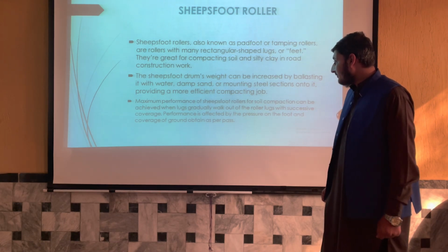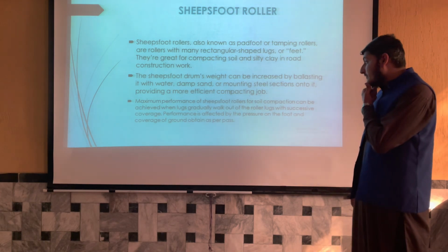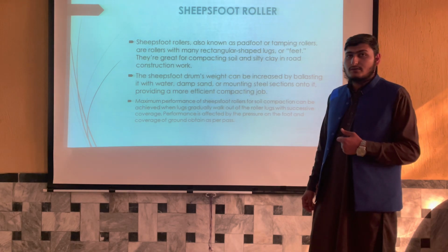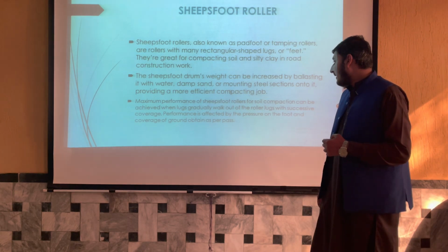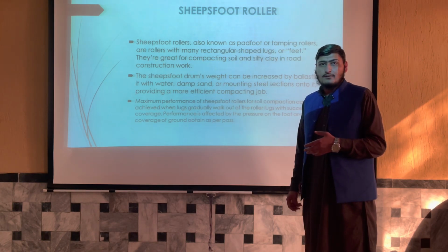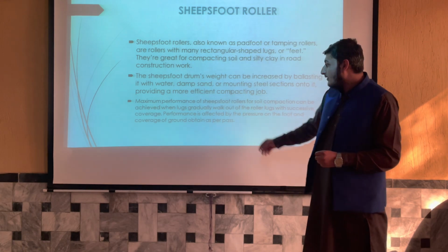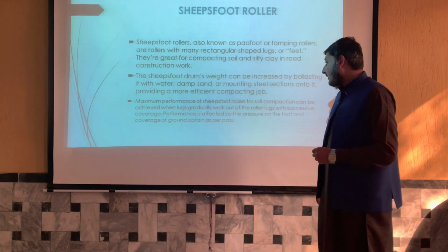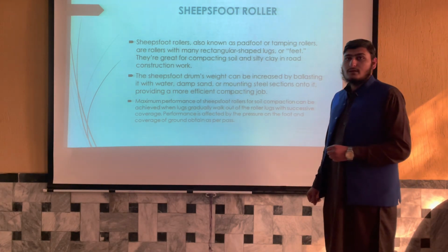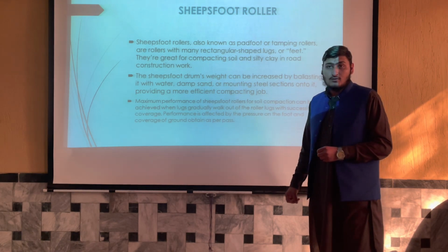The performance of the sheepsfoot roller is increased by increasing the weight of the wheel and the roller, and also by the speed. Normally its speed is 8 to 10 miles per hour, and the area covered by the sheepsfoot roller is 10 to 15% of the whole area.